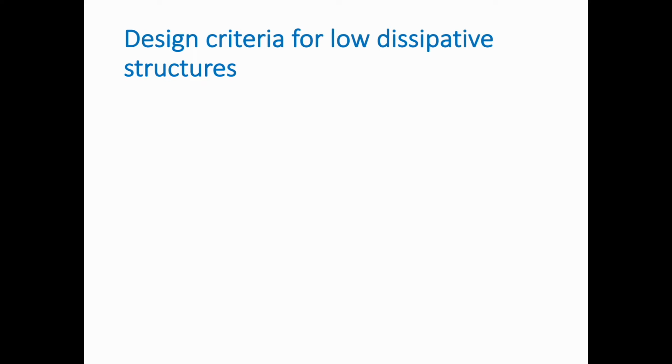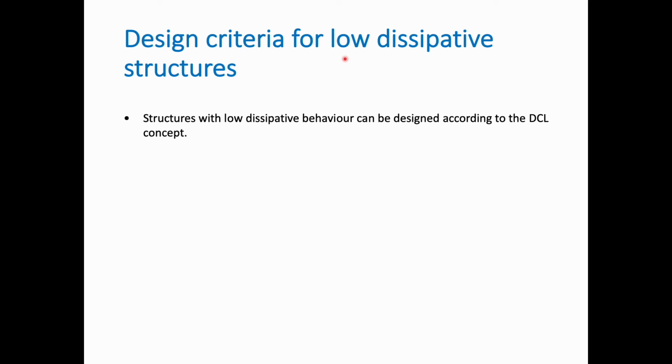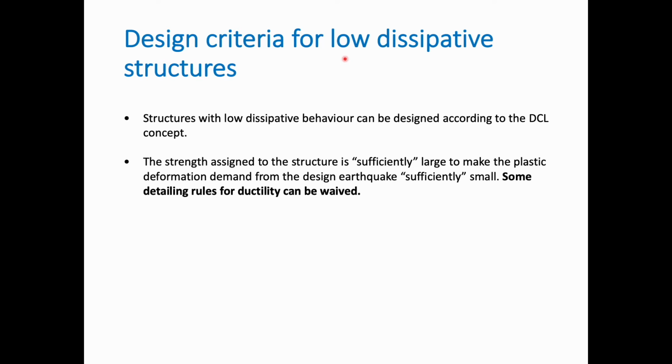Going to the design criteria for low dissipative structures, structures with low dissipative behavior can be designed according to the DCL concept as described in Eurocode 8. The strength assigned to the structure is sufficiently large to make the plastic deformation demand from the design earthquake sufficiently small, and some detailing rules for ductility can be waived.